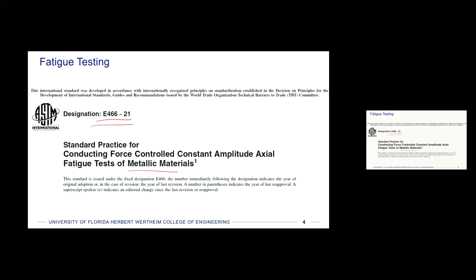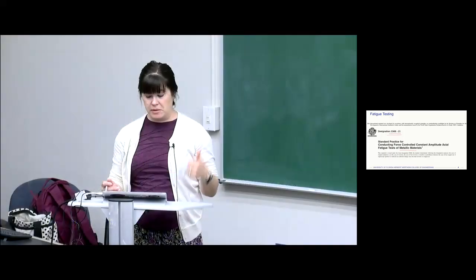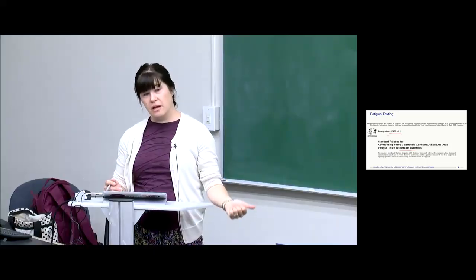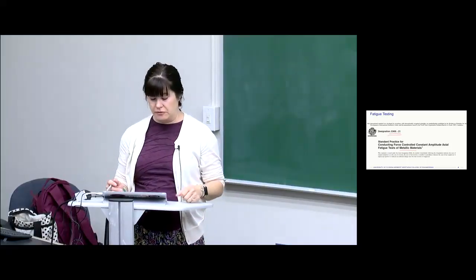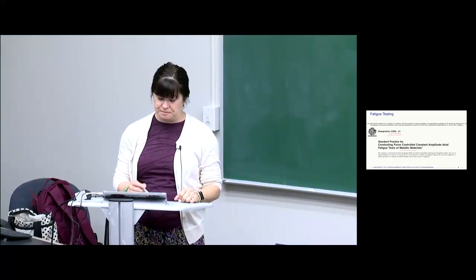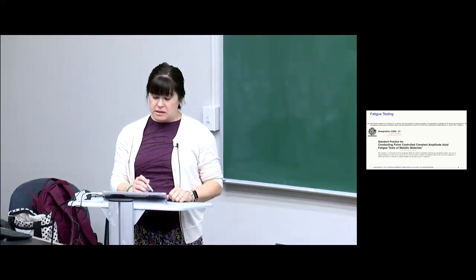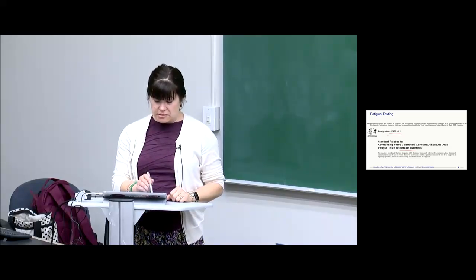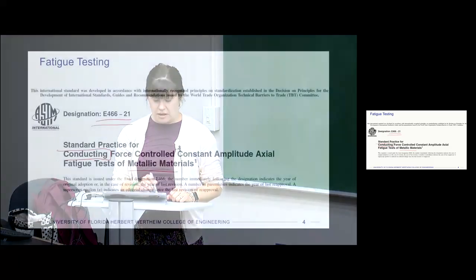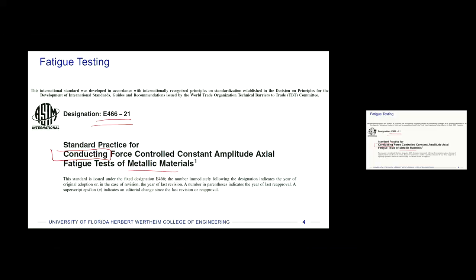Some of the things may be similar between those standards, but they may be very different based on the higher strains you might expect, and the different types of deformation mechanisms. We can see that this is about conducting the tests, right? So I'm just going to circle that word, conducting. And it says force-controlled constant amplitude axial fatigue tests, right? So this is not multi-axial. This is just single axis, right?